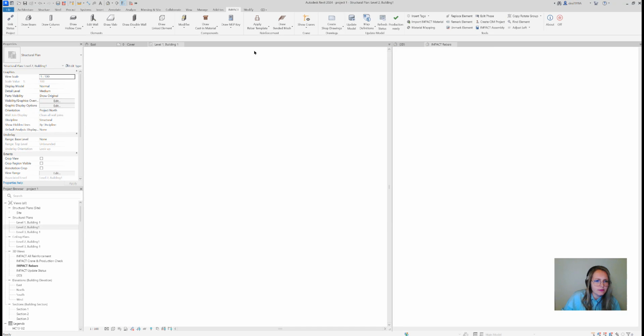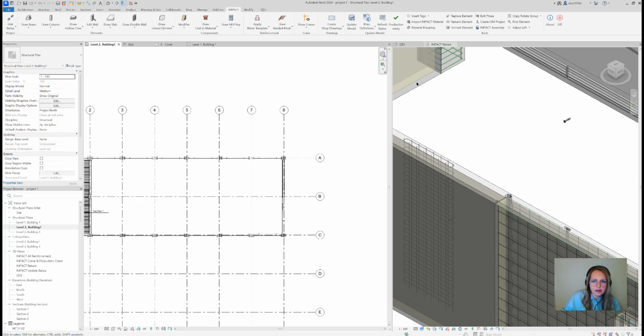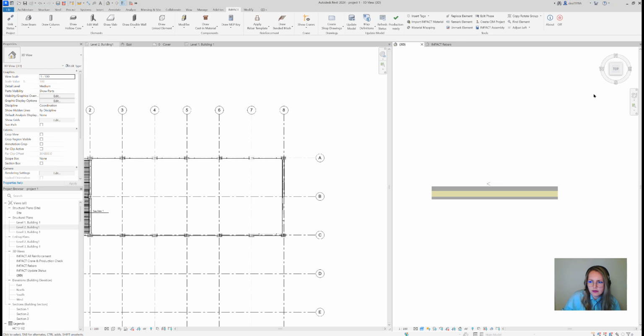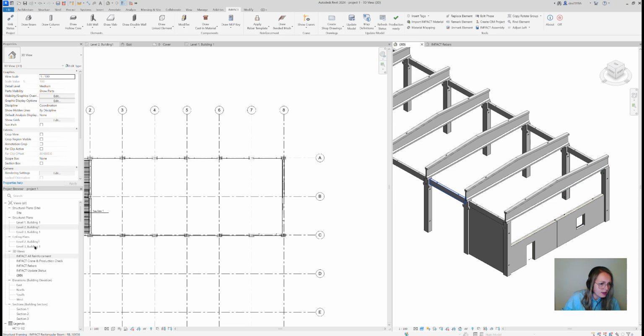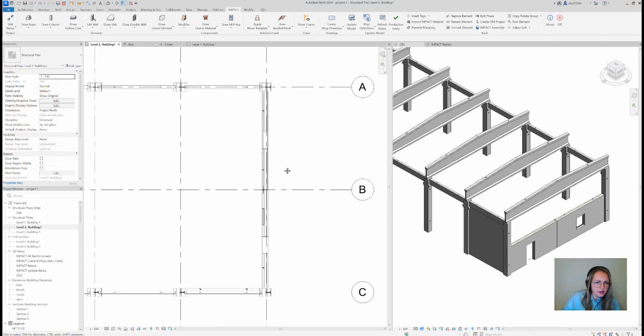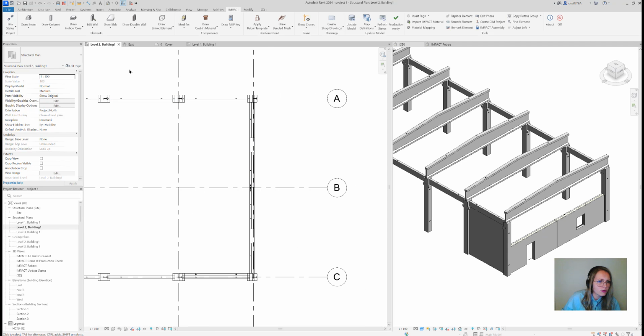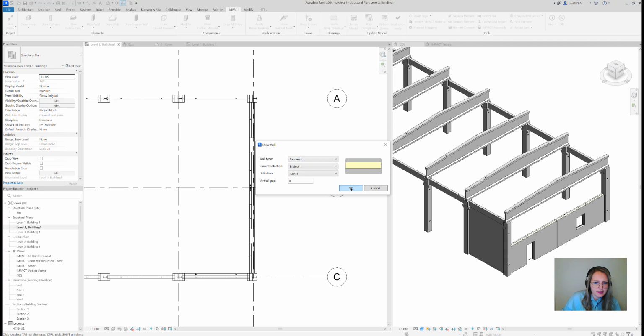Where it is, it's here, level 2, right? And I need the 3D here so I can see if I'm doing things correct. Okay, I'm on level 2 on the left side, and I'm going to draw another sandwich wall. It's the draw wall command, and here I'm going to say just okay.